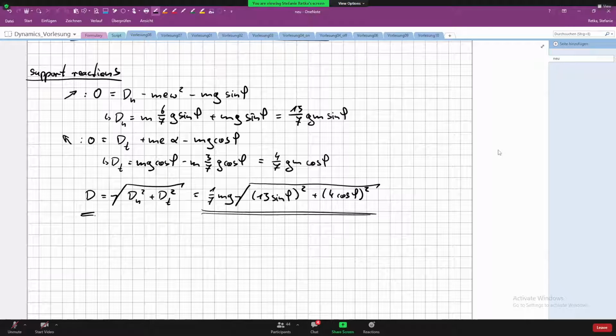And then once you have your free body diagram, then you can build the equilibrium conditions, solve for the unknowns, maybe in combination with energy conservation law or an integration to obtain omega from alpha. If you have a constant angular acceleration, constant alpha, the easiest way would be integrating alpha over time to obtain omega. If alpha is not constant, then using energy conservation law might be easier.